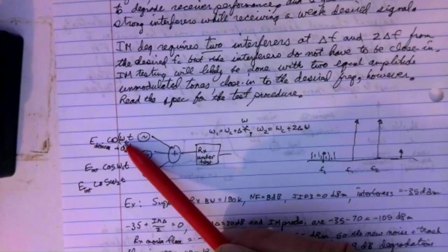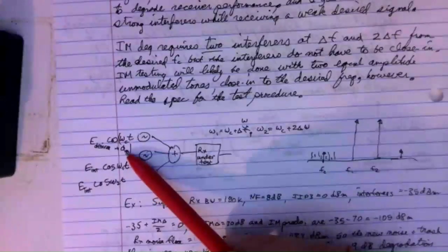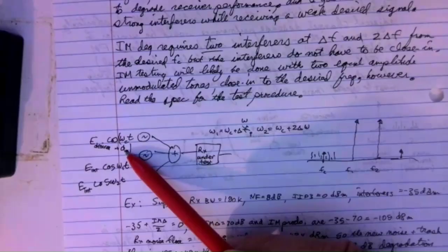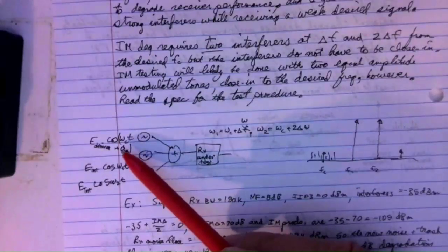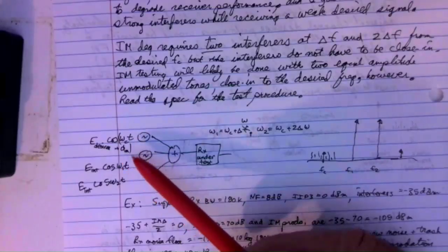It can be, but it can also be in the phase term, because phase is the integral of frequency, or frequency is the derivative of phase. And if you forget that, think about the units. Phase is in radians. Frequency is radians per second. So you can figure out which one's the derivative of which one by the units.